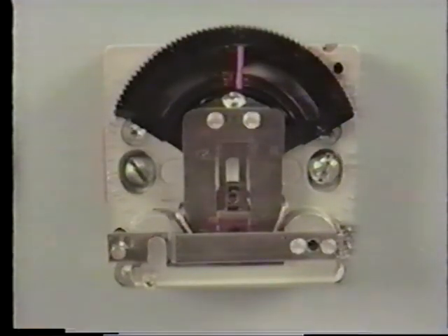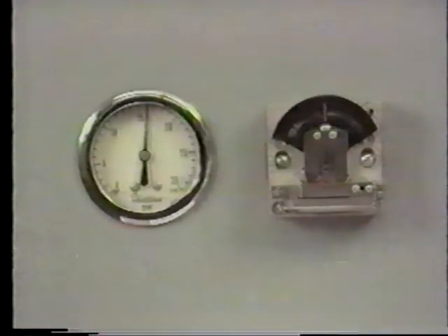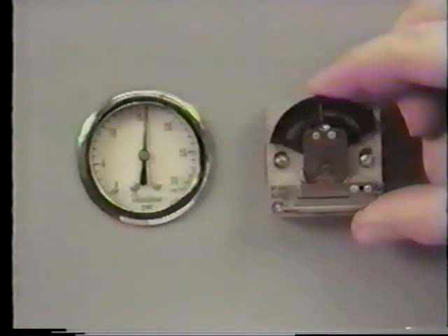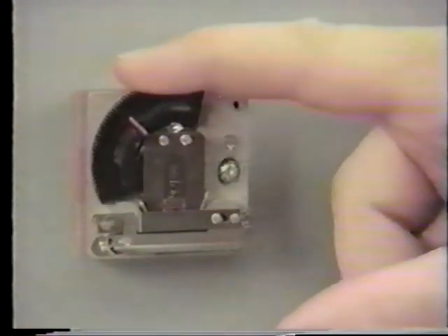The day-night thermostat has two bimetals, both with the same direct or reverse action. Each has a separate set point adjustment so that a setup or set back function can be provided. When the main air pressure is 15 to 17 psig, the day bimetal controls the thermostat's branch line output pressure. The set point for the daytime operation is set by the thumb wheel, the same as the single pressure thermostats.